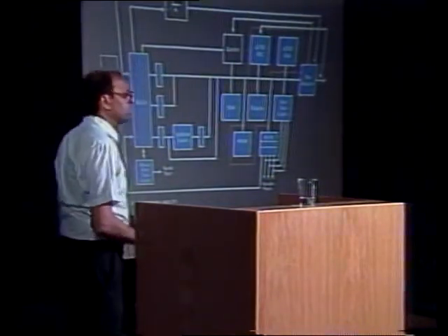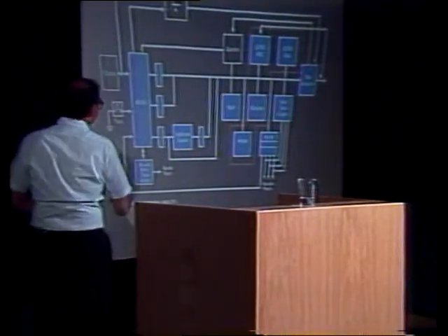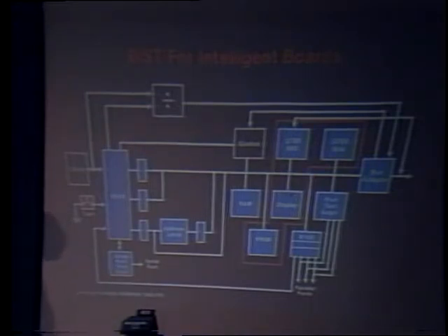Now, granted that pseudorandom vectors are not good for testing intelligent system like this, but at the board level, remember, your goal is to get chip-to-chip faults. Not your primary concern is if interconnection has failed, or if any driver has gone bad, or things like that. Not quite the internal functionality of any one of these blocks.